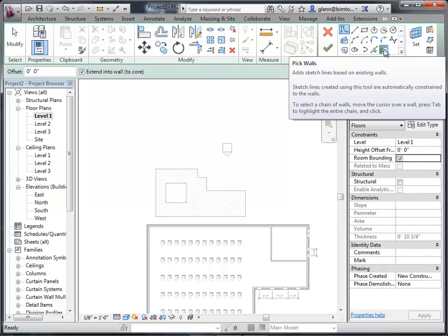Because that actually is a very useful thing to do. The idea is, as you're creating your wall, there's an interior surface, there's some sort of exterior surface to it. As you create the floor, the issue is, do you want the floor to come all the way out to the outside edge? Or do you want the floor only to come to the edge of the core and let the outside surface wrap on beyond it? Okay. And nine times out of ten, you want to have it do this. You want it to wrap into the core and have the exterior surface just wrap beyond it.